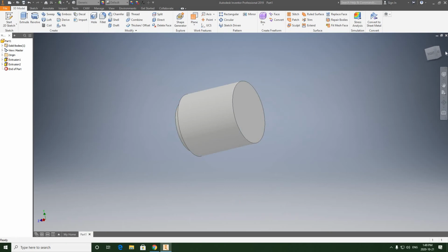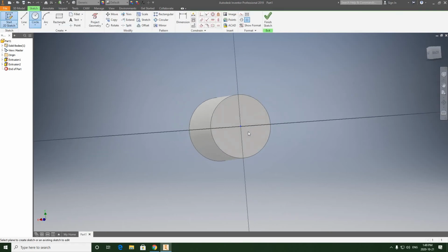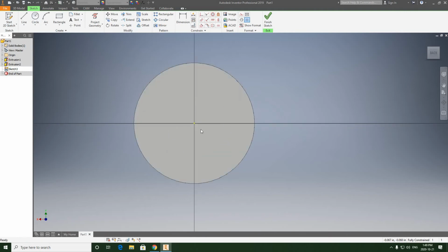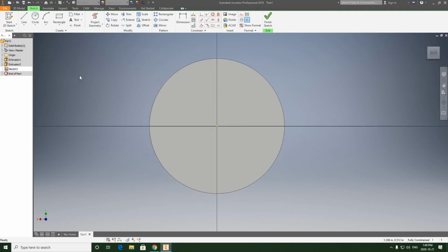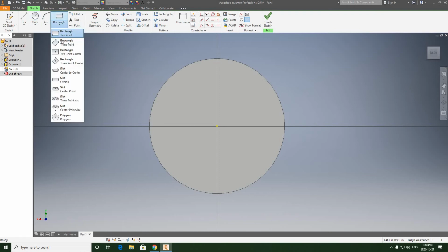All right, now turning over to the back. On this face, we're going to be creating a hexagon shape. This would be done on a dividing head, also called an indexing head, on a vertical milling machine in the machine shop. So what we're looking for is polygon, which is found under rectangle.